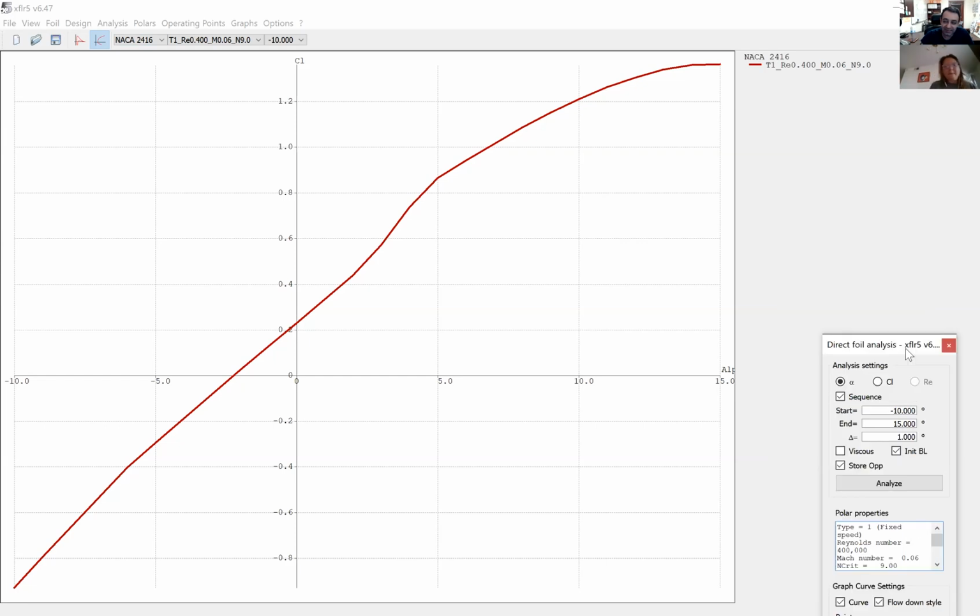So do you see this graph? Yes. So this graph shows the lift coefficient versus alpha, which is the angle of attack, right? If you remember, we discussed that as you increase alpha, your lift increases linearly to a specific angle. It's like a line. But after, for example, an angle of attack of more than 5, you see that it becomes curved, and it goes to 15, and after 15, it goes down.